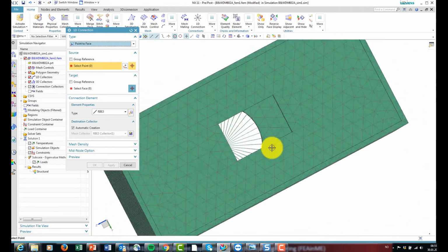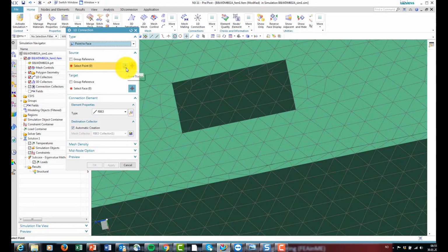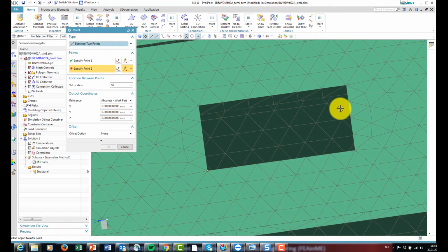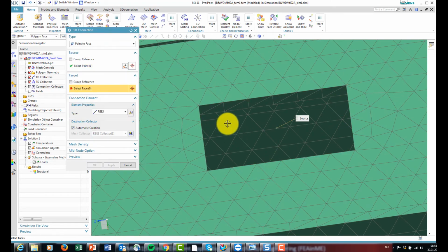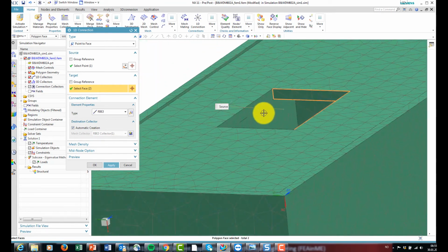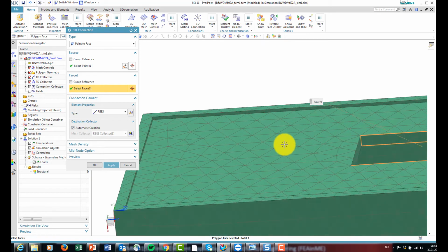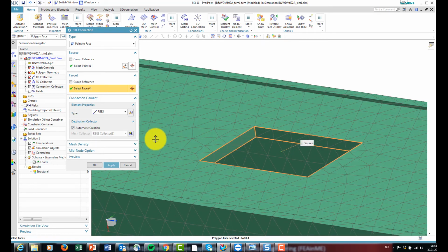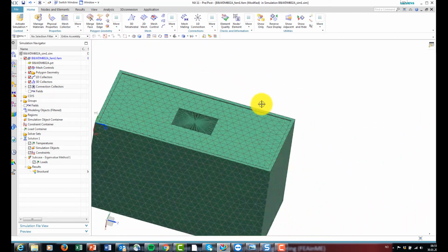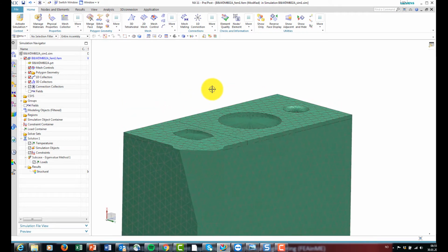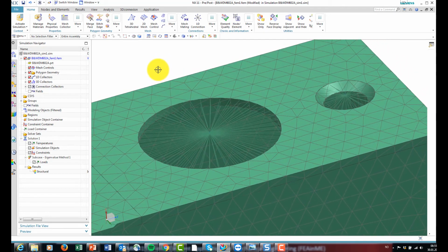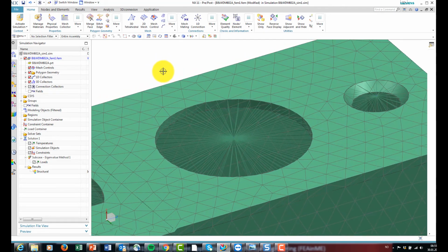And it's the same with the rear side here. I use the same dialog. I use between 2 points. Select this point and that point. OK. And the surrounding edges here. Of course, this is not really a detailed way of doing it. I just show you the principles here. And I press apply. Then I've sort of represented the stiffness of the elements. I could have done it more exact, but I don't have the properties of the elements.